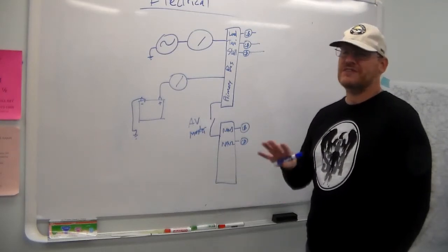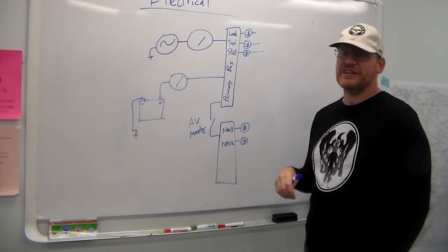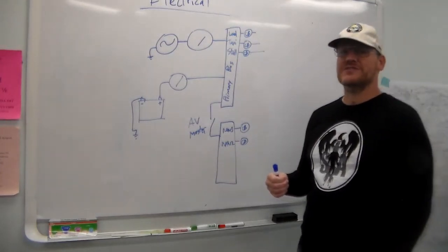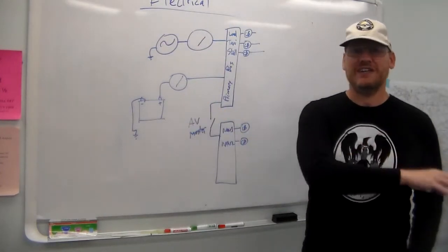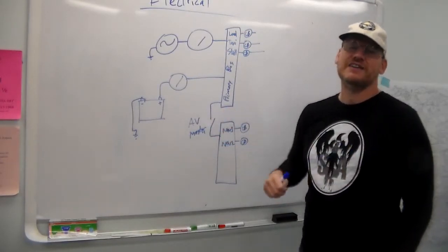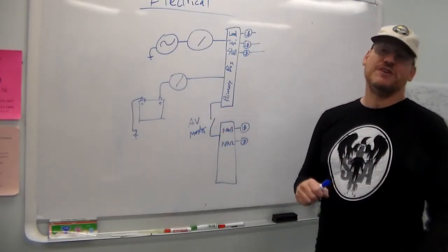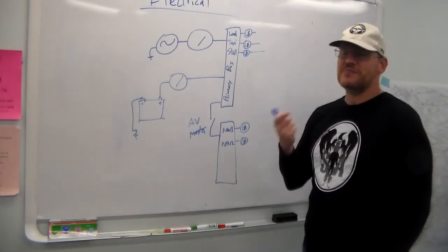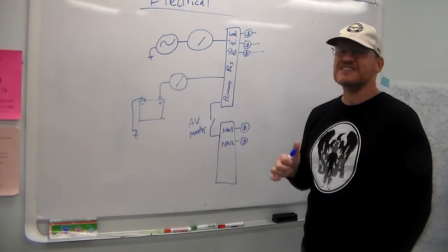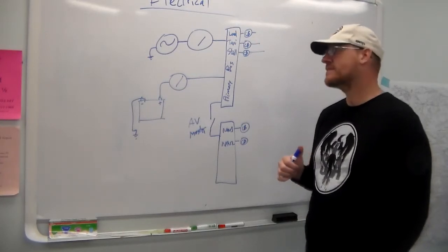So you'll have instructions in your pre-flight and your before takeoff preparations that say, check all the fuses. Some people will run their hand down the line of fuses, or sorry, breakers, and go, oh, no, none of these are tripped. They're not popped out. They pop out, there's red on the inside, so you can easily see if they're popped.